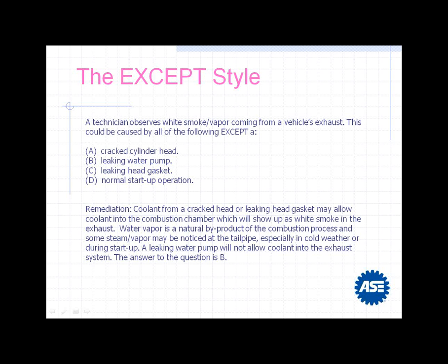Okay, so again, we have to apply our knowledge of the subject matter in this question and use our technical knowledge to make our diagnosis of this problem. So coolant, I think everybody knows, coolant from a cracked head or a leaking head gasket into the combustion chamber should show up as white smoke coming out of the exhaust. Okay, water vapor. Water vapor is a natural byproduct of the combustion process, particularly as it relates to vehicles equipped with a catalytic converter. Everybody that understands gas analysis knows that a converter helps to convert CO into CO2 and hydrocarbons into water. And so that water vapor is a natural byproduct of the combustion process.